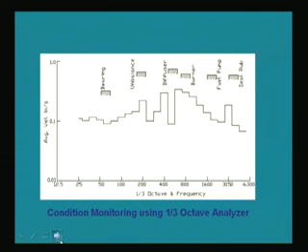So, this is another slightly improved filter, that is 1/3 octave, in which we can have a narrow band pass filter. You can see that here various amplitudes of various frequencies are plotted. This is frequency and this is the amplitude. So, some kind of variation at various frequencies, how the amplitude of vibration is changing. You can see that here this amplitude is high, and that is related to the seal rub.